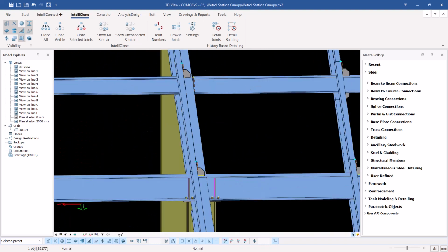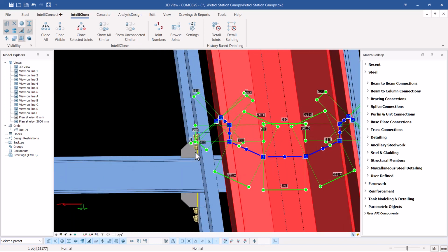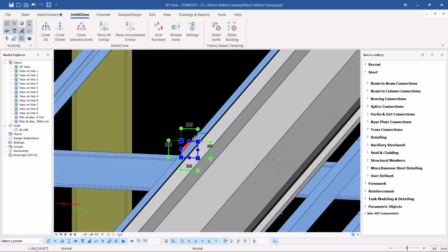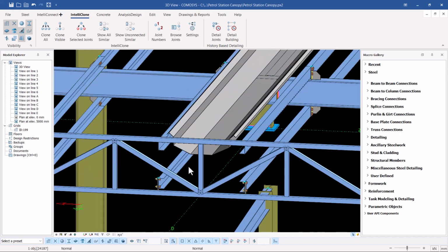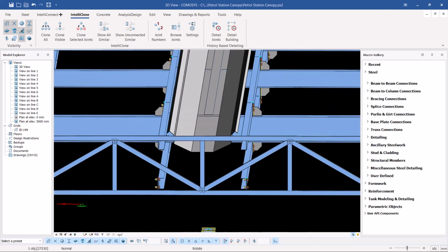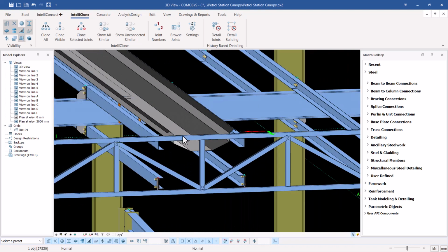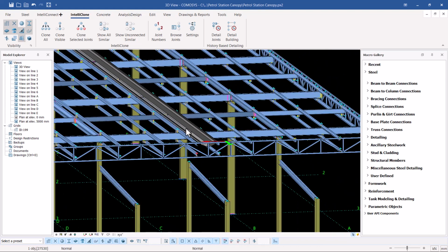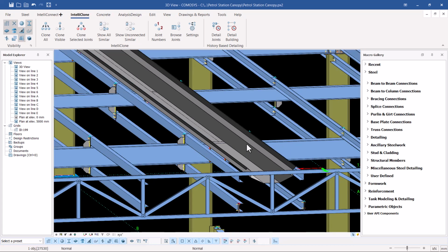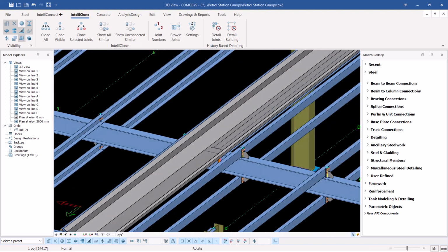And this is how you create a gutter: you create a profile and give it a thickness. Let me just select a point and we'll be able to turn that round like that. So this is our gutter, and it will be draining water from the top all the way to the bottom. In fact, we'll segment it into transportable sections, and that we'll do later on. I'll show you a special tool how we can break it. Or I can just show you here right away.